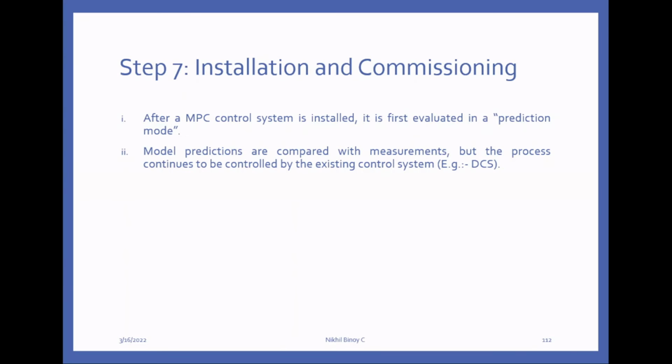So after some time, the predicted value and the actual value must be the same. Okay, so that we have to do. The important thing is, even if we are running the model predictive controller, the actual system is controlled using the conventional control system. Here we are just evaluating it. That one is not commissioning.